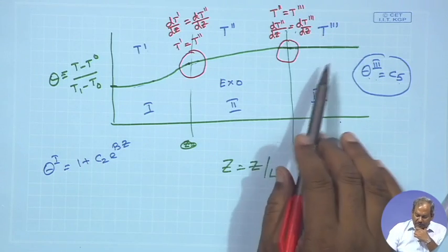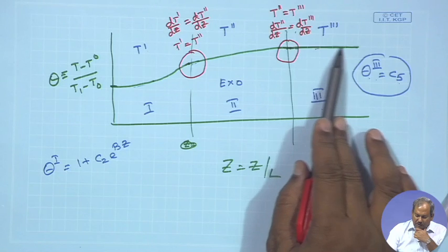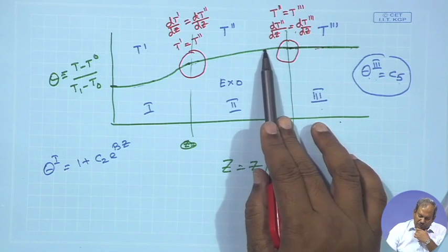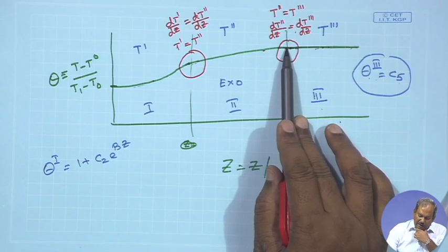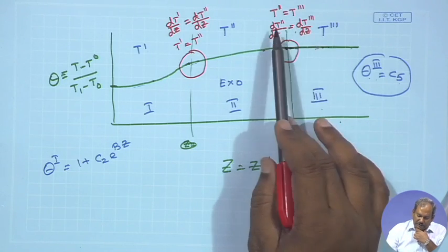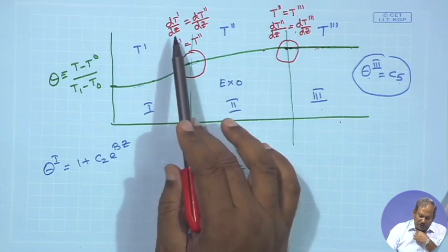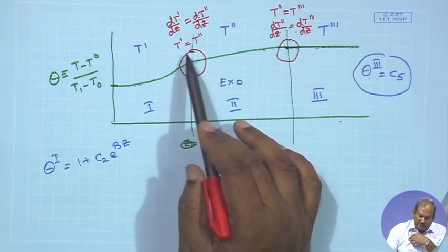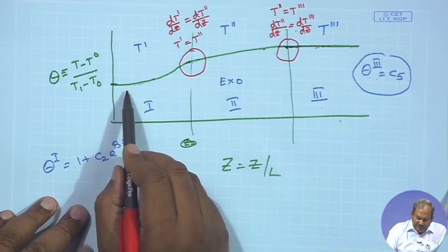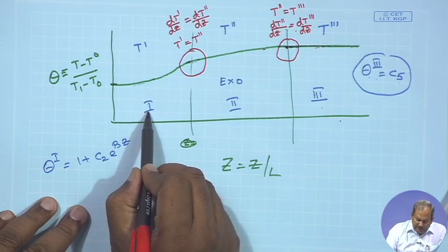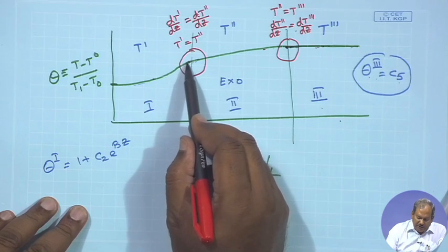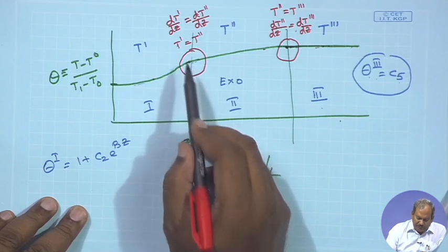So, the last condition gives me it is a constant profile. If it is a constant profile, it has a 0 slope. So, on this side it should approach the junction between 2 and 3 with a 0 slope. Okay. So, this condition has to be maintained, whereas the condition over here is like this: temperature equality and gradient inequality. So, since no reaction is taking place in zone 1, how come the temperature is increasing? That is the only question which we need to answer.